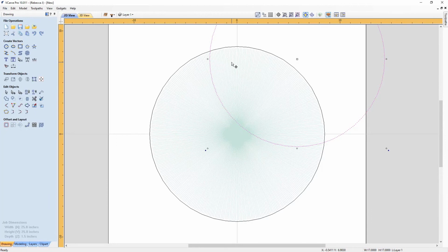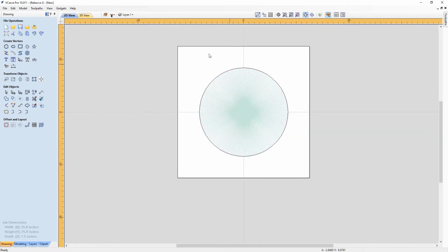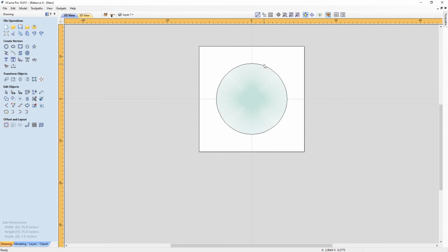Yeah, we accidentally created a second vector there, so I'm going to delete that. I'm actually just going to shrink this down a little using shift. Okay, so that's okay. And so that's our drive rail. So now we need to attach a cross section or a profile that we want to sweep or extrude around the outside of that vector.